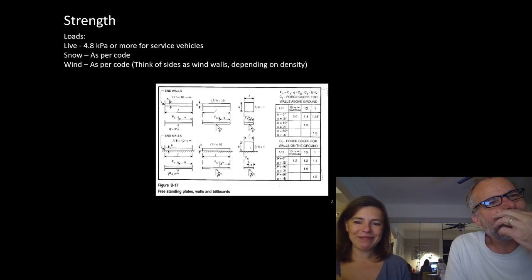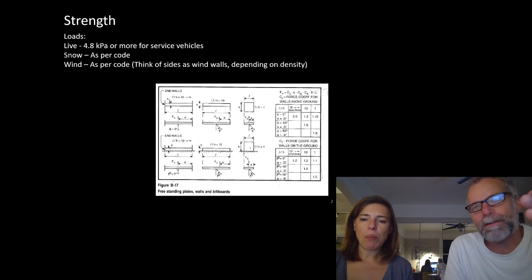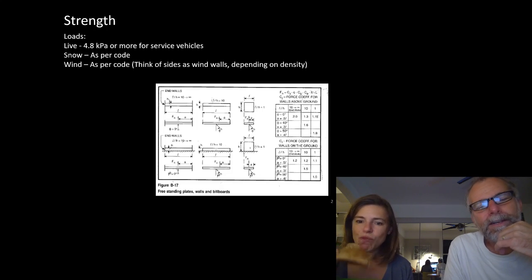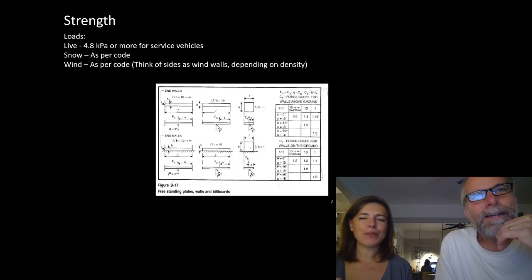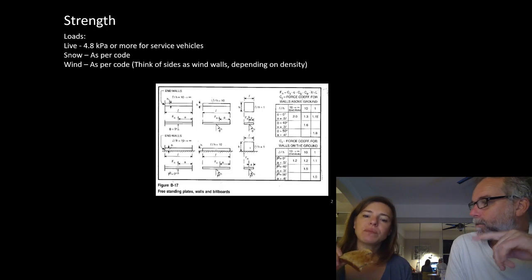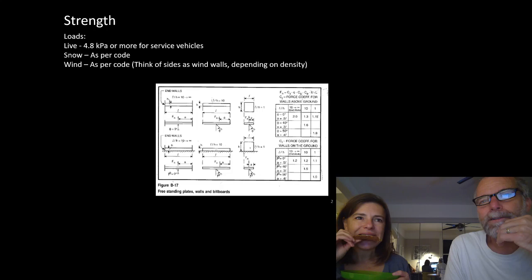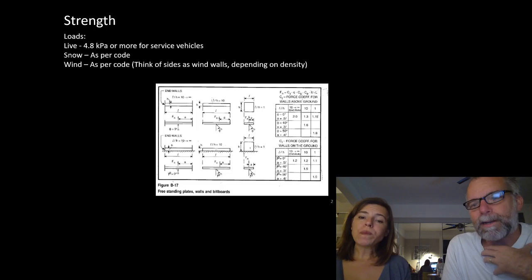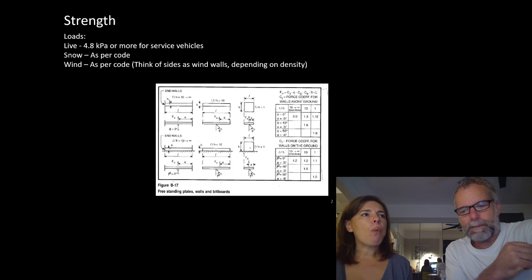That's right. So to me, live loads include occupant loads, which are really what the code refers to as live loads, the weight of the people that occupy the bridge, the snow load, and the wind load that are applied on it. Those to me are the environmental loads. Seismic as well. Actually, we don't have those on the list because it tends not to govern bridges, but that's just because we're in a low seismic zone. Seismic can be significant in a place like BC.